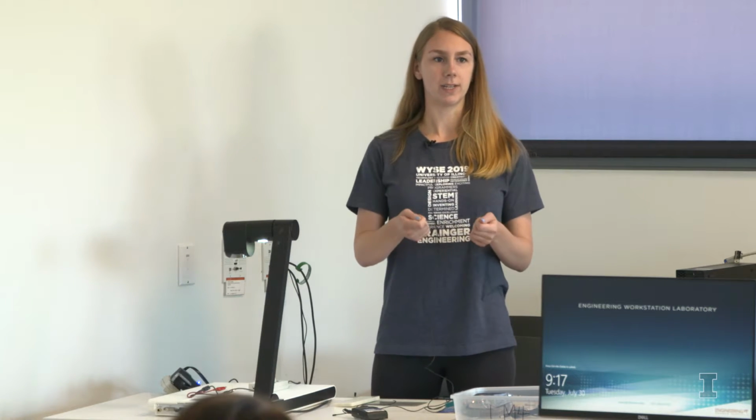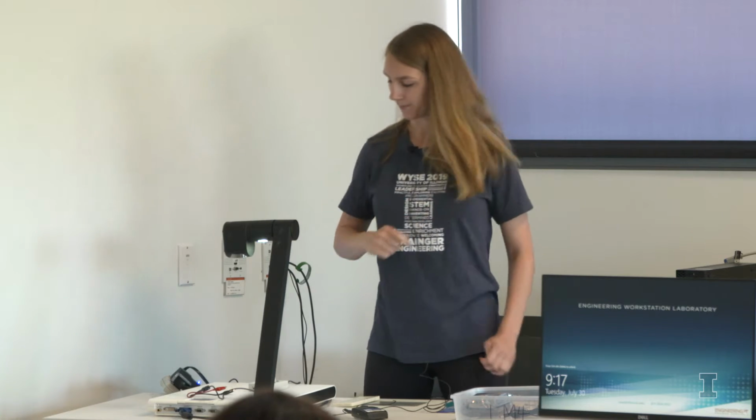So an oscilloscope is a measurement device that allows us to see a signal changing over time. With the multimeter, you can just see one value at that instance in time when you're measuring across a resistor, a voltage, a current. The oscilloscope is useful for seeing a voltage, but over a period of time. So if you have an alternating signal, you'll see the signal appear on the screen. Your y-axis is going to be voltage, and your x-axis is going to be time.